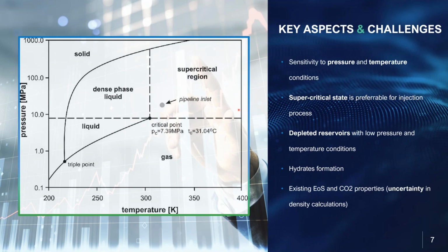Because of these changes, we might expect different challenges in the industry, such as hydrates formation, changes in injectivity, and salt precipitation on the wellbore. And we also have some uncertainty in existing equations of state, which describe the CO2 supercritical state with some level of uncertainty.